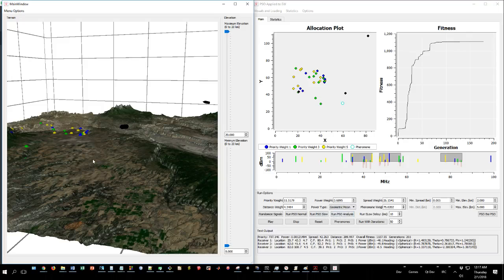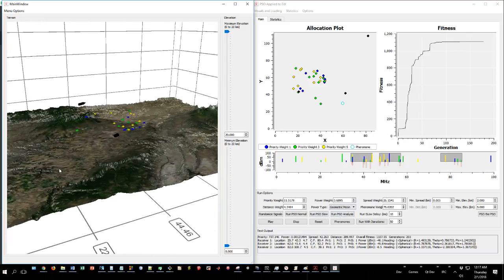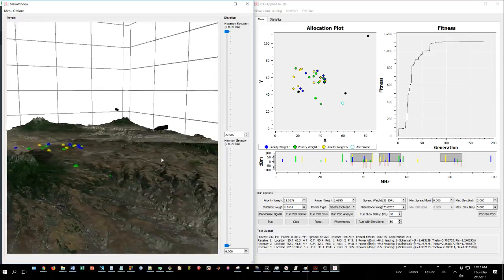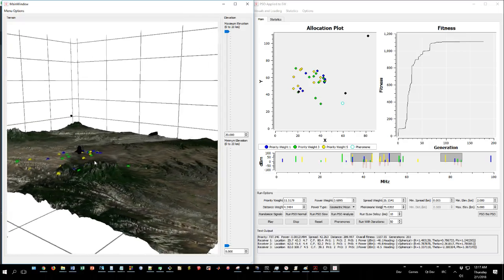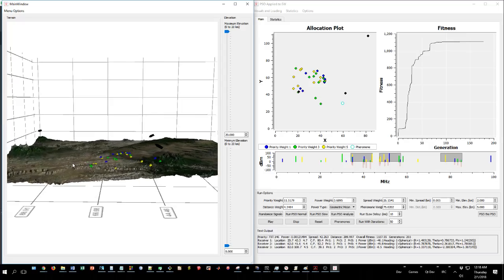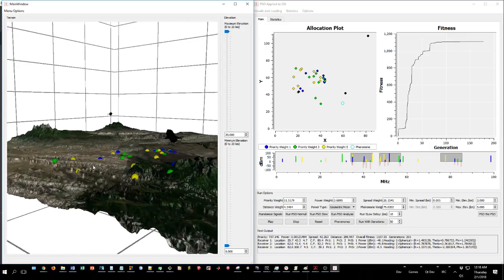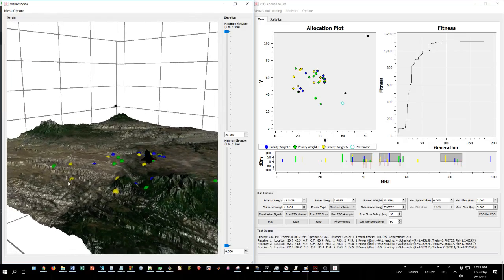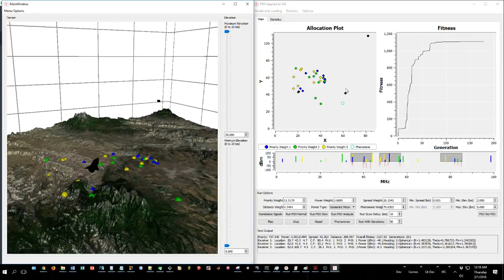So another aspect of this project that I forgot to mention is that our receivers also have a power limit. They can't receive too much power, otherwise they'll overload their feed horn and then it won't work. So if the feed horn is overloaded, then we're going to shut that receiver off so it doesn't blow up. We want to make sure that when we optimize our solutions, it's able to pick up with respect to that feed horn not being overloaded.